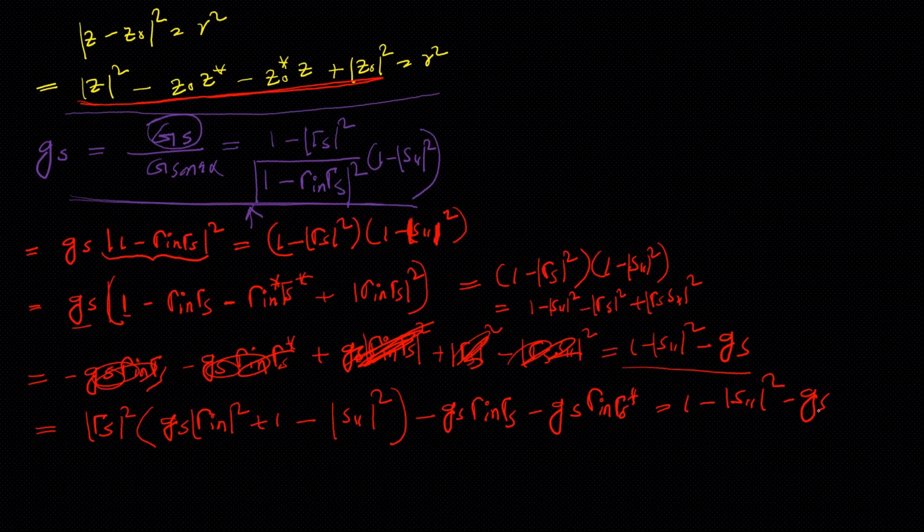Okay, now one thing you see, we have written gamma in here, some gamma in, but it is for the unilateral case, so we can write gamma in equal to S11.